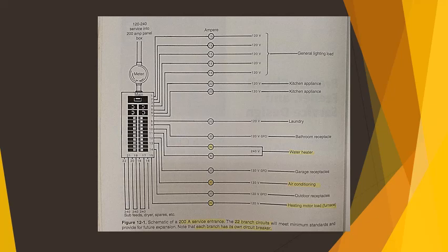Many branch circuits and feeders have utilization equipment that will not be used at the same time. Therefore, a total load on these circuits may be reduced by a percentage called the demand factor to create a lower electrical load. Throughout this chapter, you will see examples of how and when the demand factor may be applied.